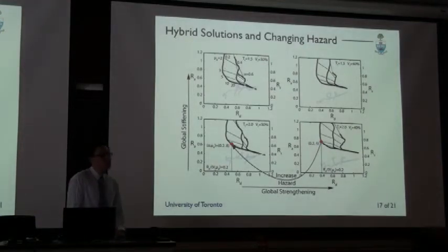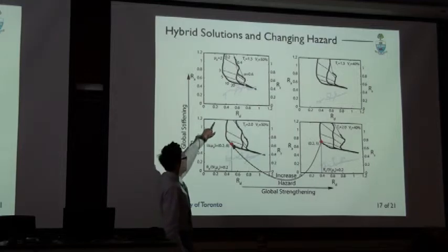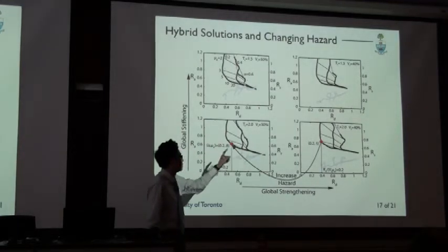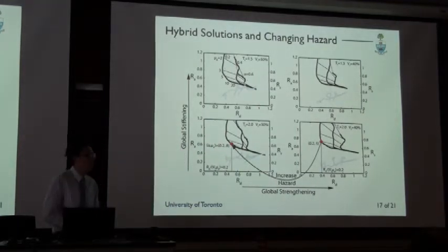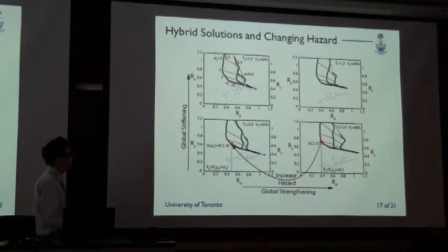Also, by rearranging the performance spectra in the matrix form, when you have different periods and strength, you can consider options where you retrofit the structure by including supplemental damping as well as strengthening and stiffening, or vice versa, weakening or softening of the structure.